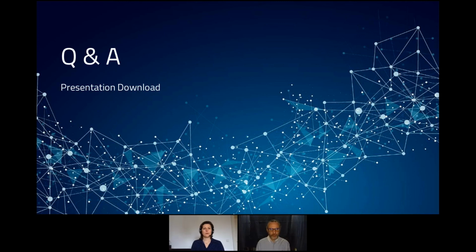All right, thanks for that, Chris. And I'm thinking just about the sampling-based profiling approach you showed. I think this is a very interesting approach to enable tracing without the on-chip trace logic. But maybe how about adding instrumentation and using the debug channel to the terminal output? Wouldn't that be an alternative and better?